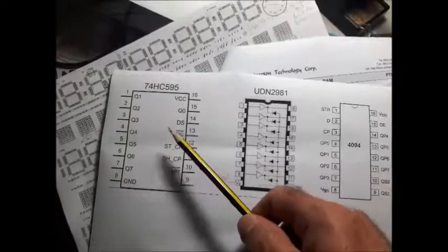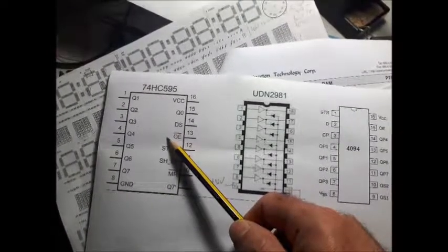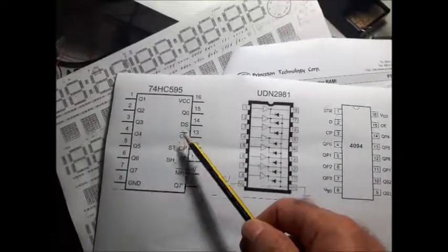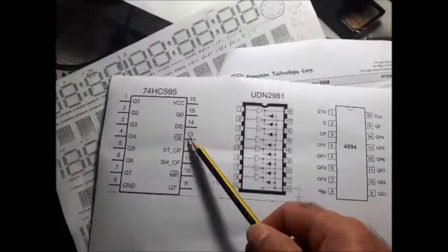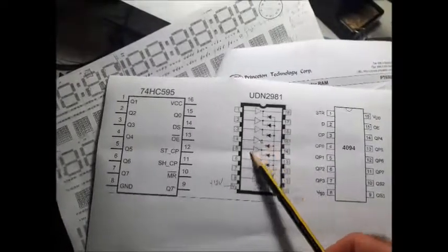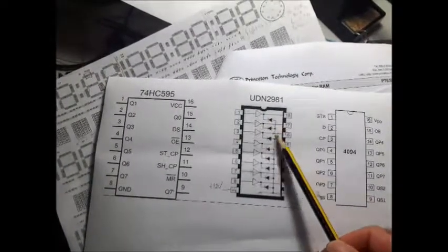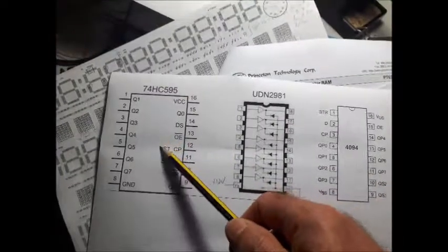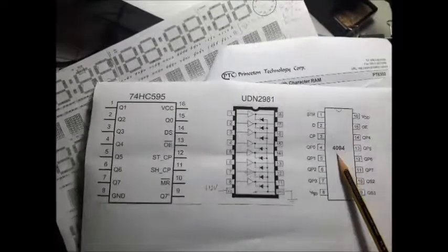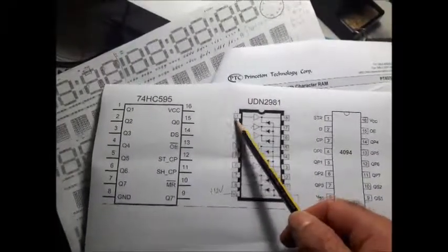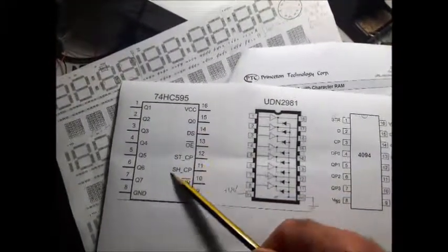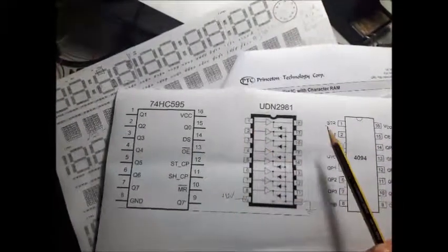If I use the 74HC595 instead of this IC, I need to convert all the pins from this IC connected to the VFD through other UDN2981s. In this case, if I use 7 of them, I need 7 UDNs. With the 4094, I only need 1, because it makes the conversion of 5 volts to 12. In the other case, I need to convert all pin outputs of the ICs to 12 volts. Okay.